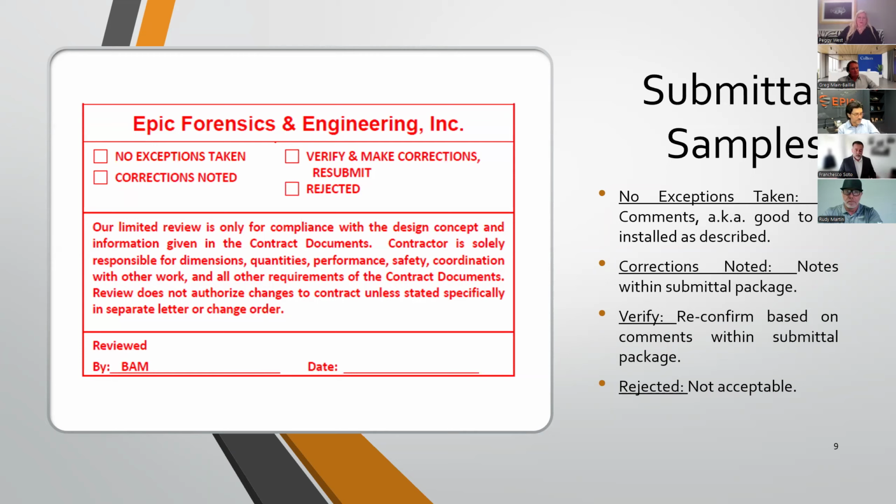Working with Greg and the Owner's Rep, I try to insist that there's real specificity on not only the material, but actually the method for installation of that material. It's really critical because when you find out later on that the waterproofing is not performing and there's no instructions on how to do it, well, now you're just litigating. Now you're just trying to figure out who messed up. If you have a submittal that actually has specific instructions, like a Setco type product where you have to do shiplap installation, that is very powerful to protect you as the owner when you're pursuing a potential claim to see who is actually responsible.